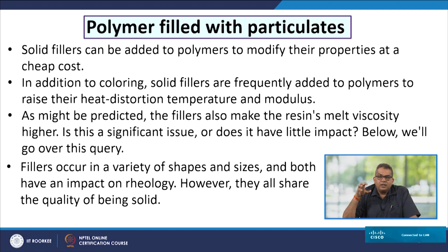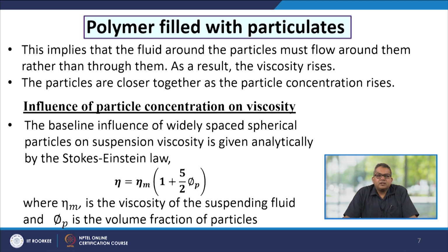The fillers occur in a variety of shapes and sizes, and both have an impact on rheology. However, they all share the quality of being solid. This implies that the fluid around the particle must flow around them rather than through them. As a result, the viscosity rises. Now, the particles are closer together as the particle concentration rises. Now, the influence of particle concentration on viscosity.